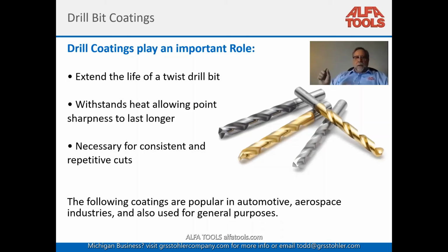If you take a standard high-speed twist drill, the point, corners, and the chisel edge in the middle will start to break down between 600 and 700 degrees. It's 62 Rockwell, you're reefing down on it, you're trying to drill a 1-inch deep hole in some kind of metal, heat starts to build up, you're going to dull out the tool.